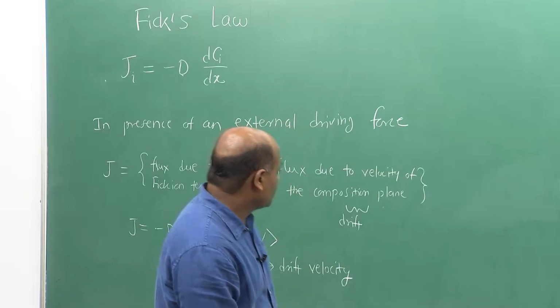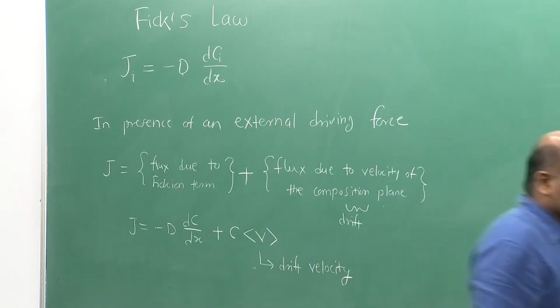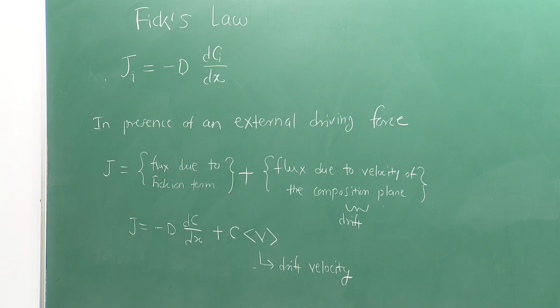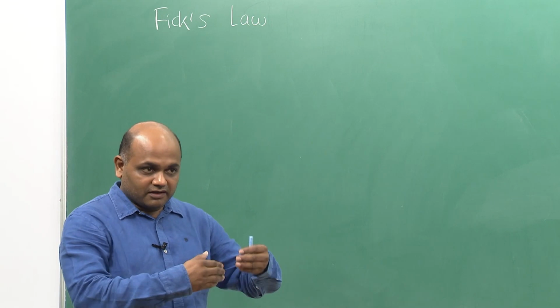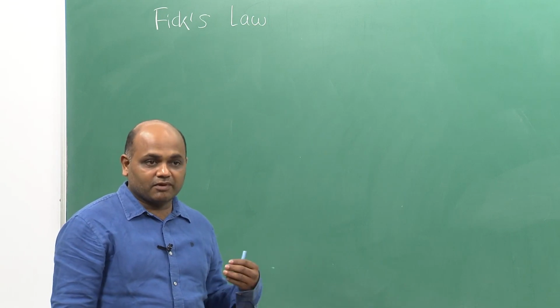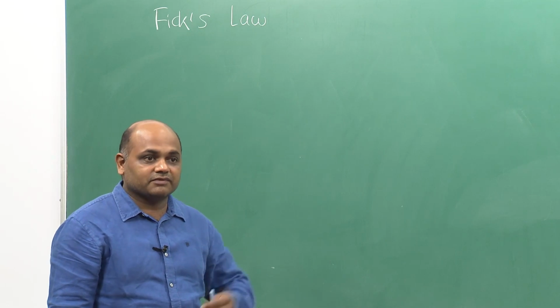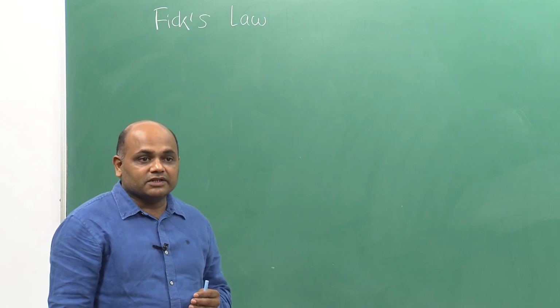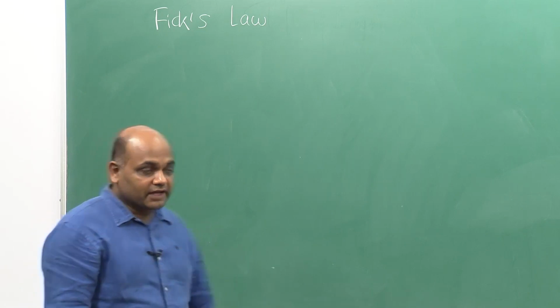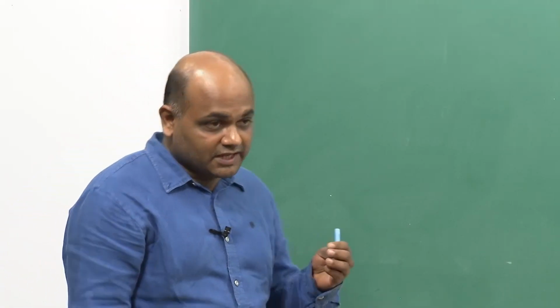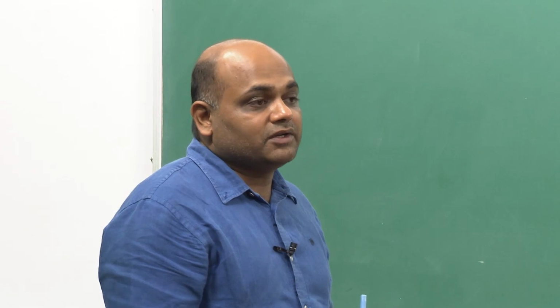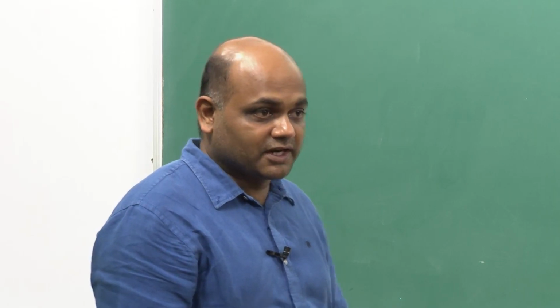Clear? Okay. So, now let us come to the diffusion in solid. Now, we say in solids diffusion occurs by discrete atomic jumps, right. There are interatomic planes and the atom jumps from one plane onto the next plane or within the plane itself, right. So, it is a discrete atomic jump process, whereas here in the phenomenology we assume a continuous concentration gradient, right. So, let us now see how these discrete atomic jumps give rise to the net flux down the concentration gradient, right. So, let us try to link the two.